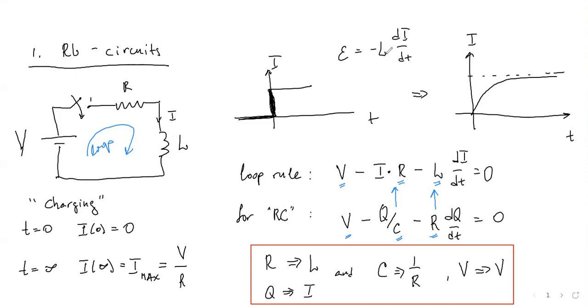But once you have non-zero inductance, you have a non-zero time constant, so it's going to take some time, tau, to build up this current. In the example we work with, the inductance is millihenry, so we are talking about milliseconds.